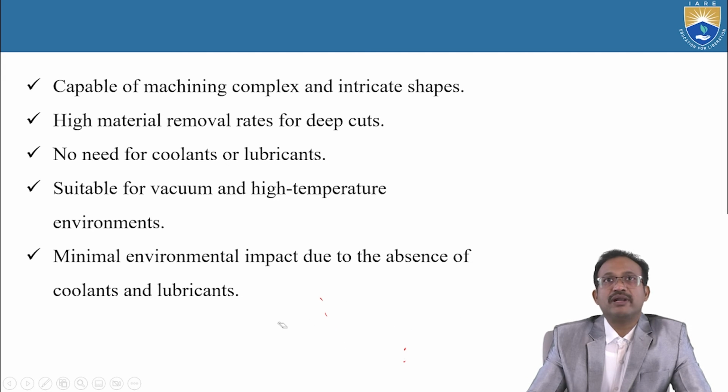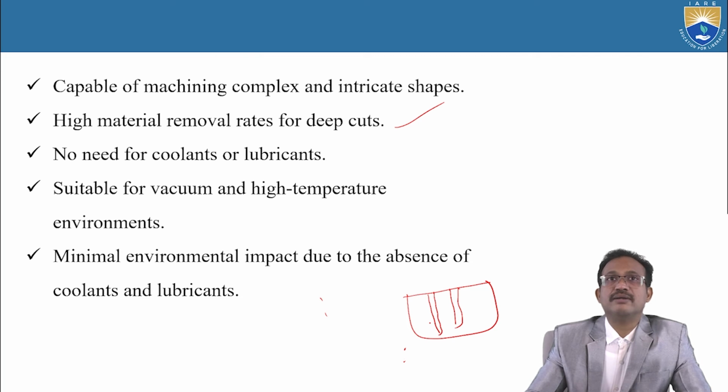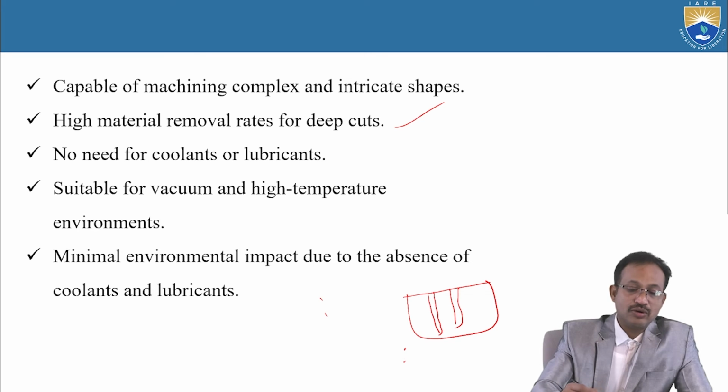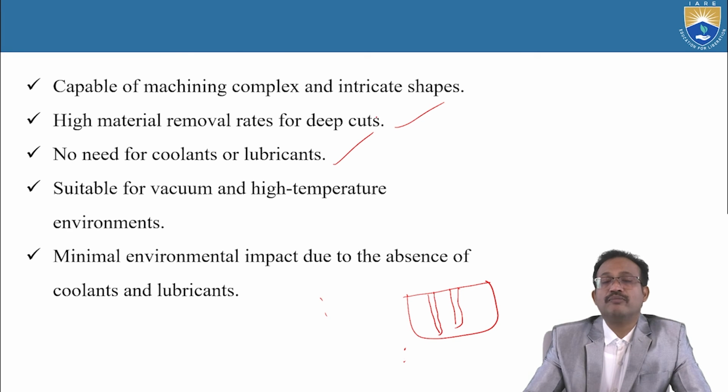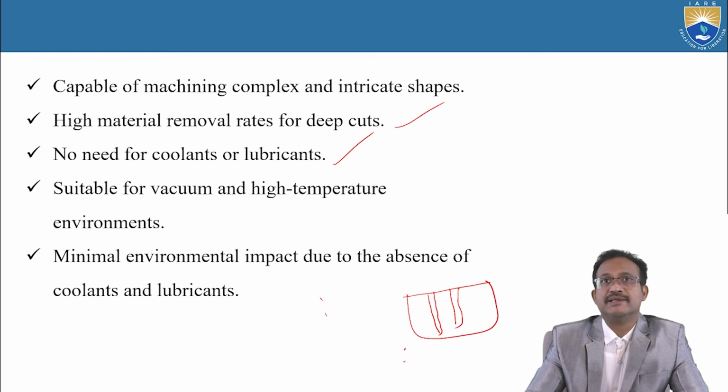High material removal rates for deep cuts. Whenever we want deeper cuts, high material removal rates will be possible. No need for coolants or lubricants while machining. There is no direct physical tool, so there is no question of friction and heat generation. So no need for coolants or lubricants.